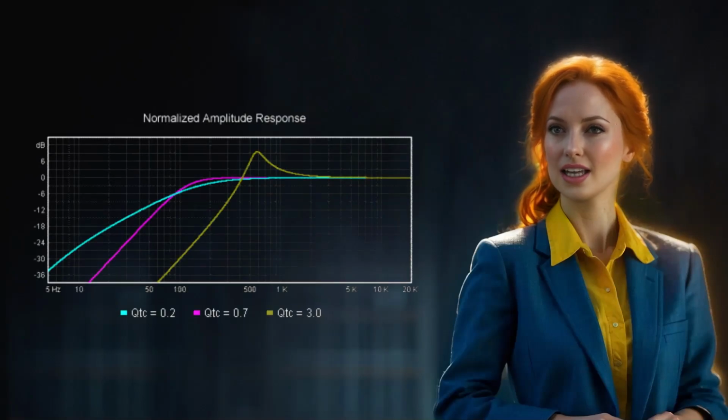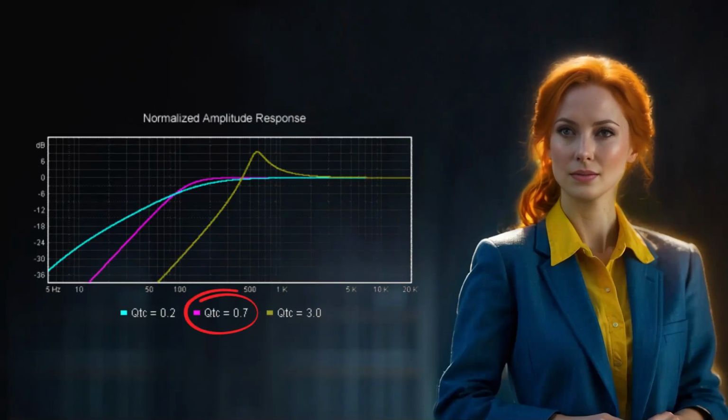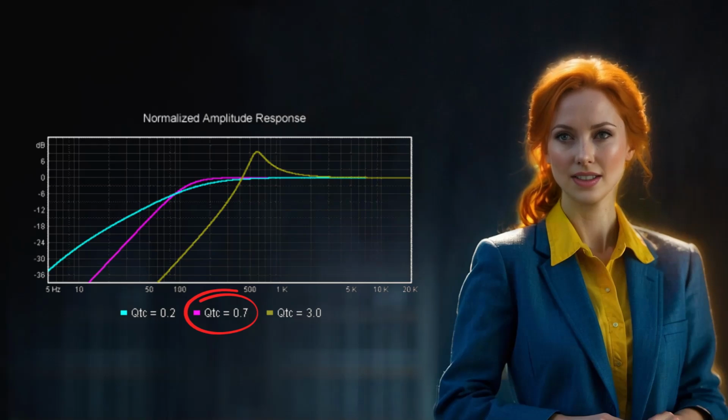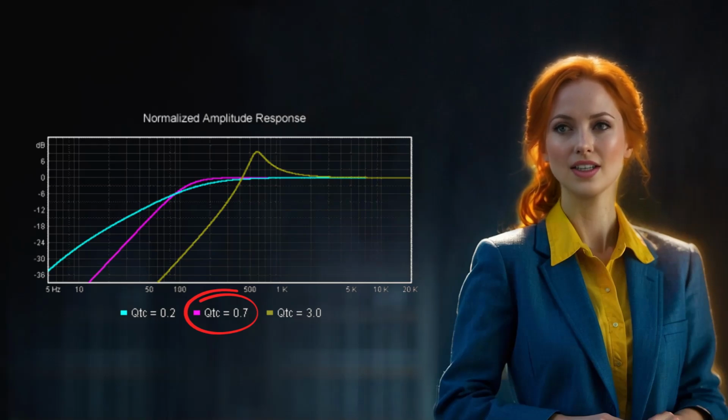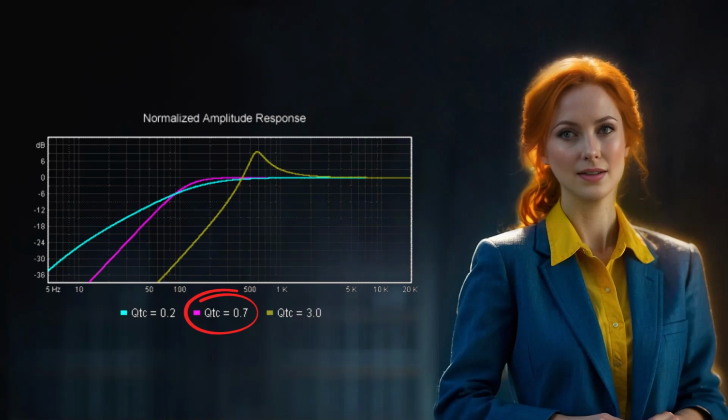When designing a speaker, the quality factor of Q equals 0.7 is often regarded as the reference point to start. This value provides a flatter frequency response above the resonance frequency, yet ensuring the bass is not overly compromised. Many sealed and ported speakers take the liberty of manipulating this value for a better tailored bass response.